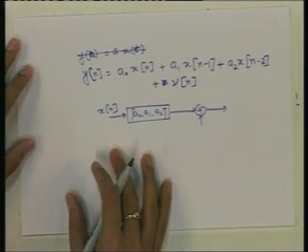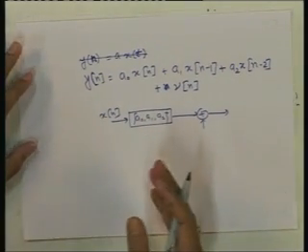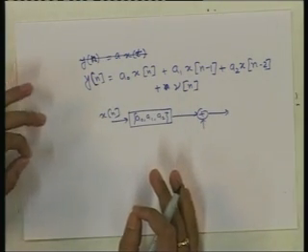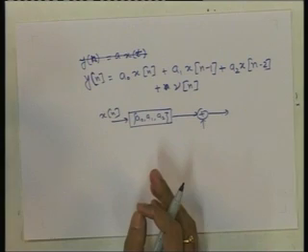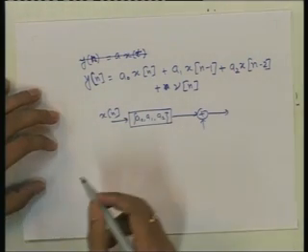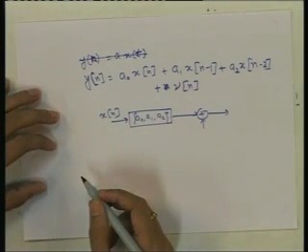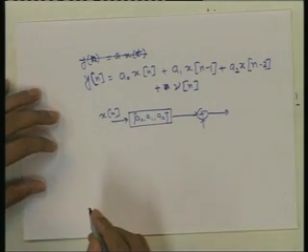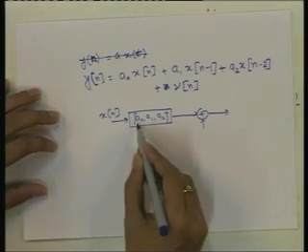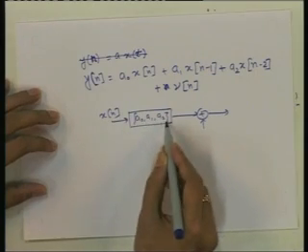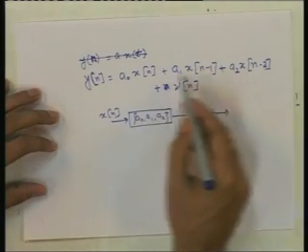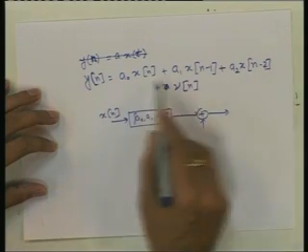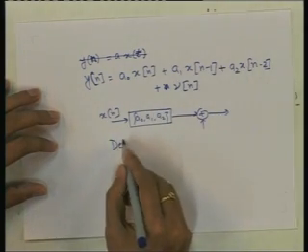Now, there are different parameters of the wireless channel which specify how fast the channel is changing with time, or how much multipath is there, and such other things. For example, the length of this impulse response. So, in this case the length is 3, 0 to 2. This length is called the delay spread.